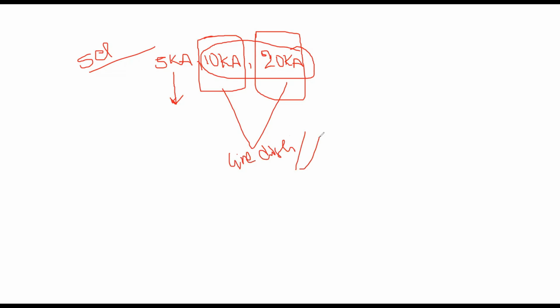The line discharge class, as I discussed before, can be presumed in a way that a long transmission line charged to a certain overvoltage will discharge through this connected arrestor in the form of a traveling wave, as we discussed before.